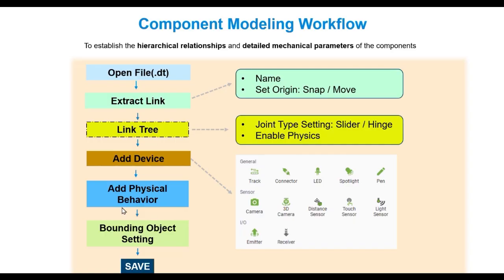And finally, if you have some devices, a bounding box may need to be set. Bounding box means they have a physics relation to each other. If you just place features in DIATwin, they will not collide with each other; they will just penetrate. But if you add a bounding object, it enables a physics relation from component to component. That is just a quick guide. After this page we will do our devices one by one, so you will know what the structure is.